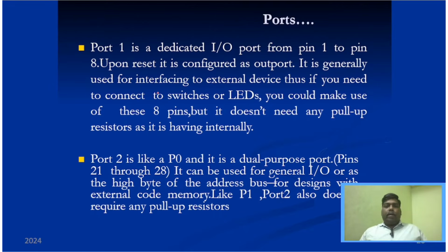For port 1, it is a dedicated input output port. It is not dual purpose. As I said, out of 32 input output pins, you have 24 pins as dual purpose, and the 8 pins which are not dual purpose, which are a dedicated IO port, are port 1. Mostly port 1 is used for interfacing switches, LEDs, keyboards, everything. That is the purpose of port 1, a dedicated IO port, and it does not need any external pull-up resistor because it has an inbuilt one.